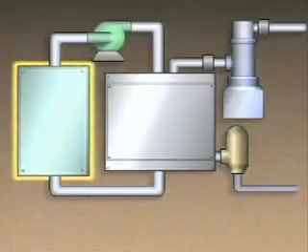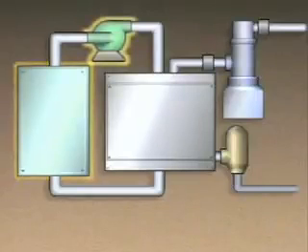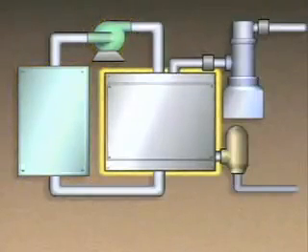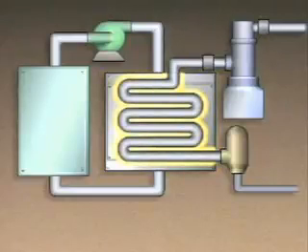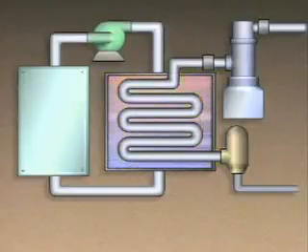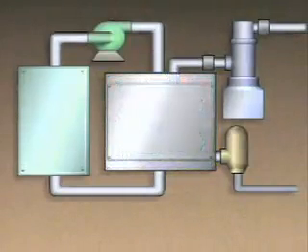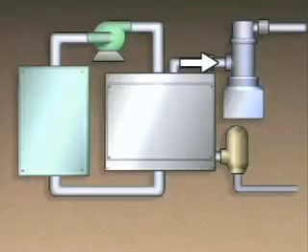The brine flows through the process equipment where it absorbs heat and cools the equipment. A pump is used to create flow through the brine cooling system. The brine is then pumped to a heat exchanger. The heat exchanger in the brine cooling system is the evaporator in the refrigeration system. In the evaporator, the brine acts as the heat source, and its heat is absorbed by the refrigerant. As the refrigerant flows through the evaporator, it changes to a vapor. The refrigerant then flows on through the rest of the refrigeration system.